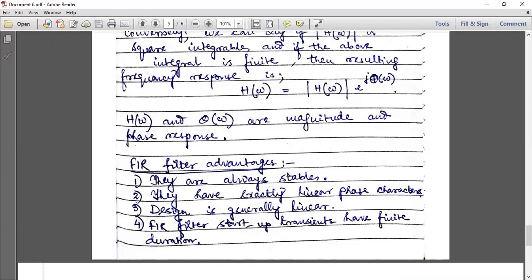Clear? However, an IIR filter has lower side lobes in the stop band than an FIR filter having the same number of parameters. Therefore, if some phase distortion is either tolerable or unimportant, an IIR filter is preferable as its implementation involves fewer parameters.